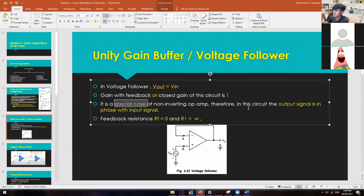Okay, so therefore, in this circuit, the output signal is in phase with input signal. So how do we know that the output signal is in phase? That's because your input is in the non-inverting. So can you guys still remember? If your input is in inverting, you have a positive input, it will become a negative output. But for the non-inverting, whatever is the sign of your input, it will not change anything. Okay, so it will stay as it is. So yeah, it's in phase. Okay.